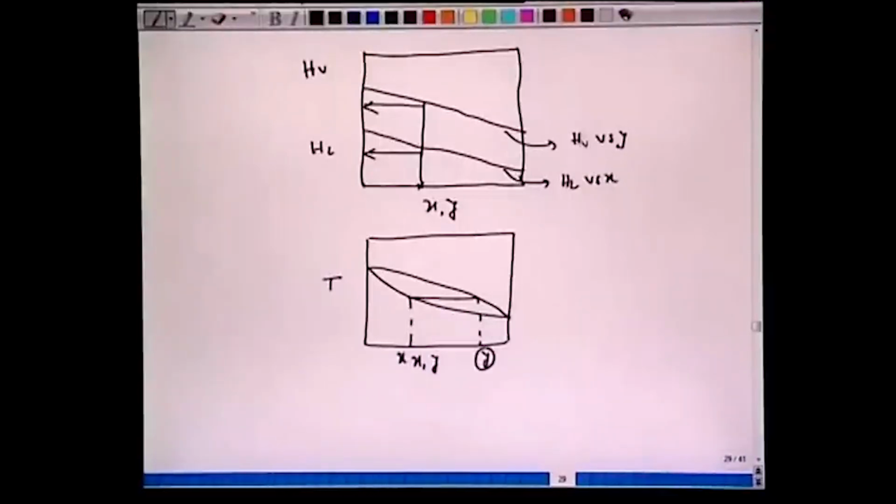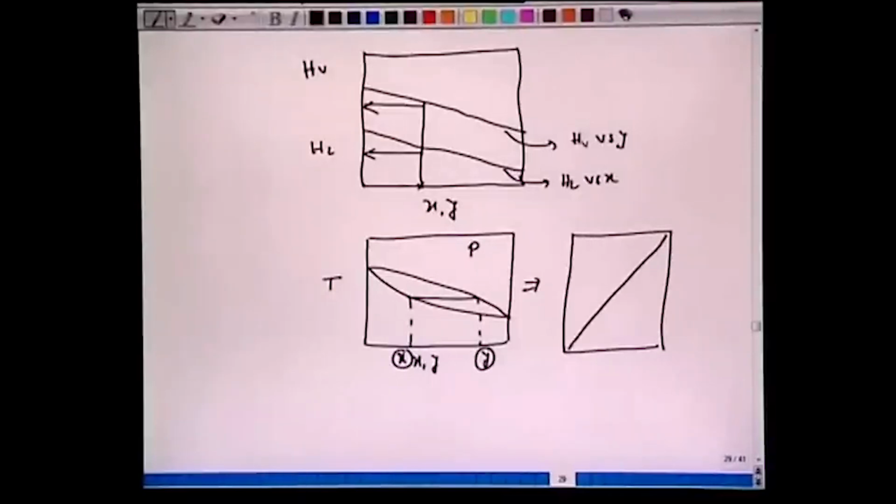So if we have Y and X fixed here for a given pressure and temperature, we can also generate, if you recall, the Y versus X diagram. So essentially we can also have an equilibrium curve like Y versus X. We take a component projection from here for X, bring Y to this 45-degree line, and then extend here to obtain this coordinate. Similarly we can obtain other coordinates here. So we have Y versus X, and we have the TXY diagram.